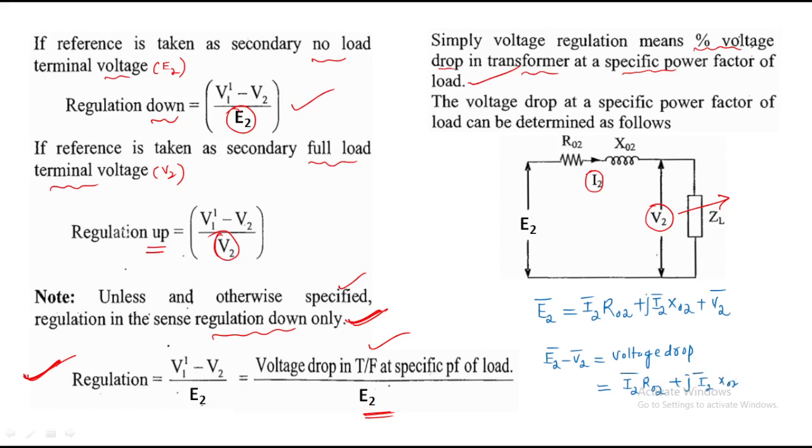This is the voltage balance equation from this circuit. The regulation is then (E2 minus V2) by E2.